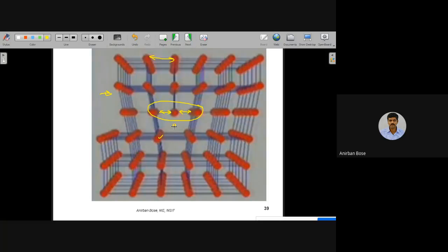On the other hand, just below this point, you observe that the distance between these atoms is quite large in comparison with the regular distance in a perfect part of the crystal. This will happen if you draw a line perpendicular to this region. Around that region is the defective region. Here you can see some compression strain energy developed, and here some tensile strain energy will be developed. So this is the imperfection.